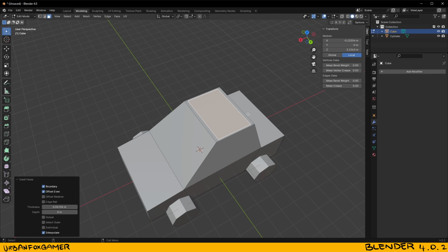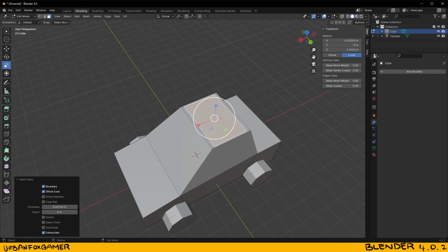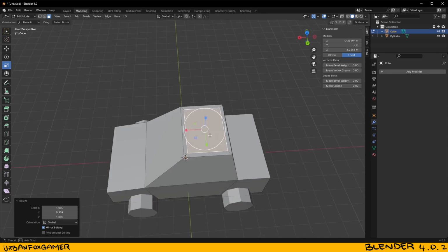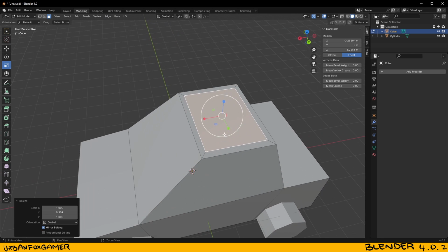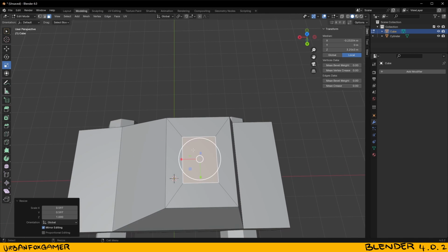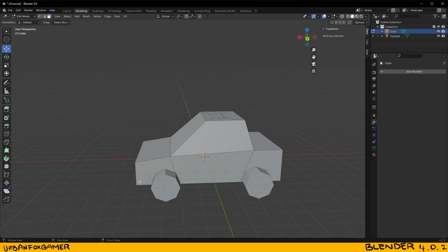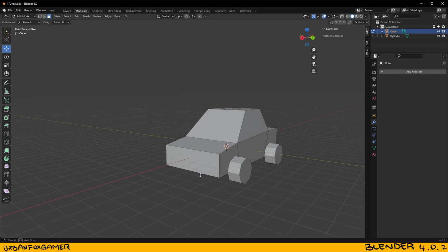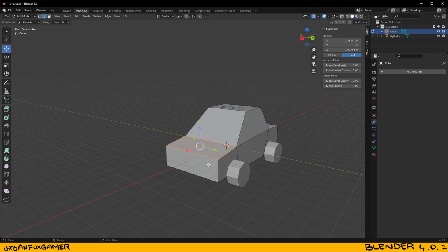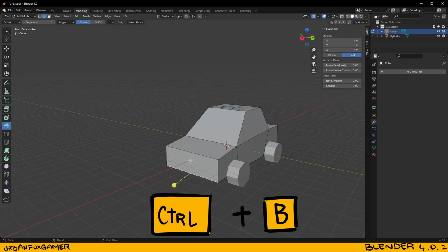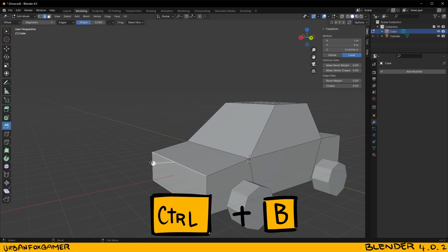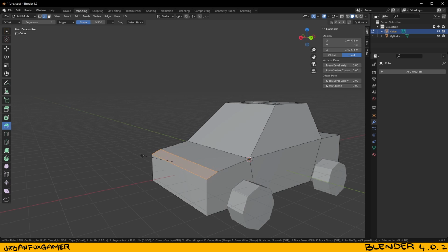After that, we can just do our custom refinement by just doing a scale like so. If you want, make it smaller. So this is like a sunroof, so it's supposed to be smaller. So I want a little extrusion like that. For the bevel, let's make this one a little bit curvy. Let's go to edge by pressing 2. Now for bevel, let's Ctrl B. Let's select the edge. There you go. We're going to bevel that side.